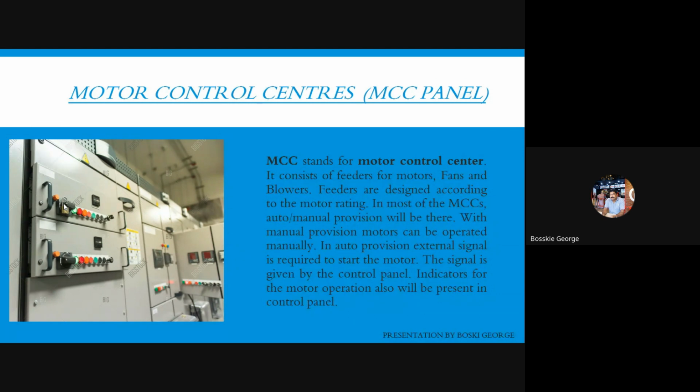When a motor starts, a high current flows through the motor windings, which may burn or damage them. So we have to reduce the starting current. This is the main criterion for selecting a particular starter.